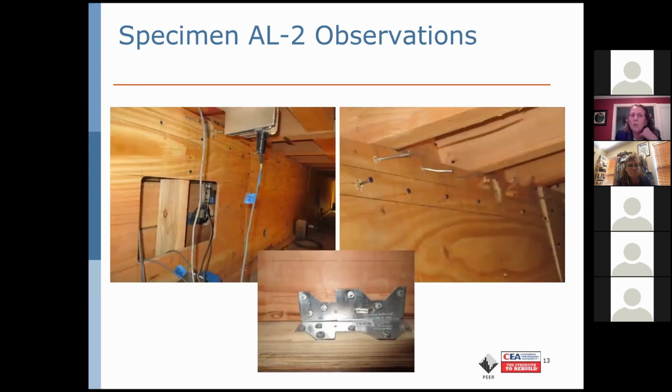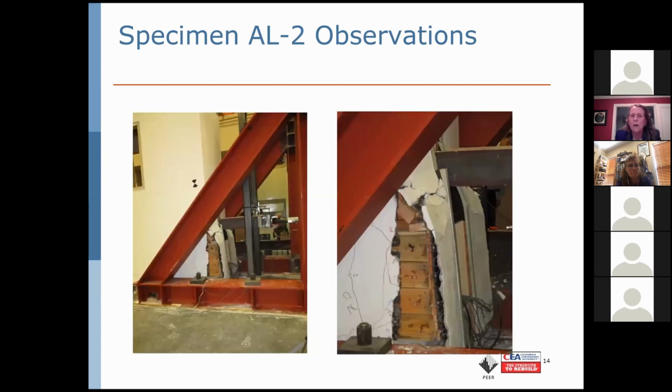We came to the conclusion it happened because the nails had been staggered between the upper and lower top plate. We actually found out in time to go back to the ATC 110 FEMA P-1100 group and talk to them about getting all of the nails put in the upper top plate in order to eliminate that failure mode.